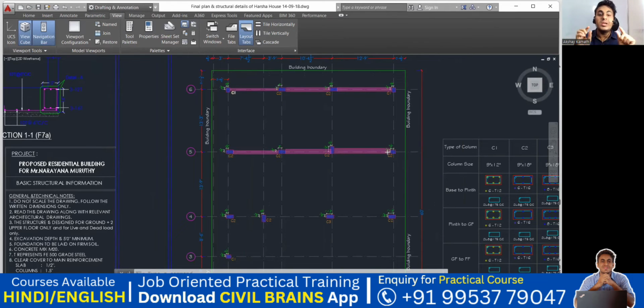Now, the main rule is that whenever you are doing a plinth beam, the main idea behind that is you have to tie the column in at least two directions. So what I'm trying to tell, for example, let us say this is my column. Is this column tied in two directions? No, because this beam is only tied in this direction. I have a space either to tie it here or here or here. Anyhow, I don't have anything here. So I'll try to tie it in this direction. Can I connect a plinth beam here? Of course I can do that. Next, for this column, can I connect in this way?